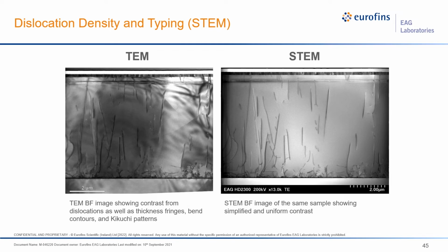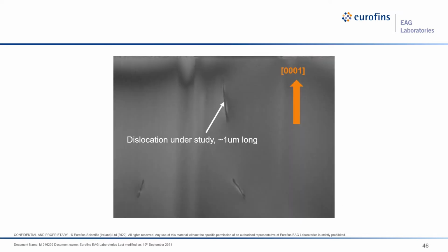the contrast of TEM is pretty complicated, for example this kind of bending contour. But if you switch to scanning mode on the exact same sample, the image is basically flat, so it is more eye friendly. For most industrial problems, scanning TEM is probably enough to have a general impression about the sample. Now, some clients